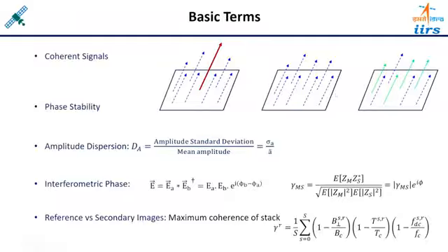At the same time, you can see on the other side, in this particular resolution cell all the scatterers are of the same type, but the response from all the scatterers is not very strong, or you can say it is of moderate scale. So if we acquire such images at time t1, t2, t3, and then calculate the coherence or correlation between t1 to t2, t2 to t3 like that, the coherence level is not very strong, that is a moderate coherence. And in this other case, if you calculate, the coherence value will be very high.